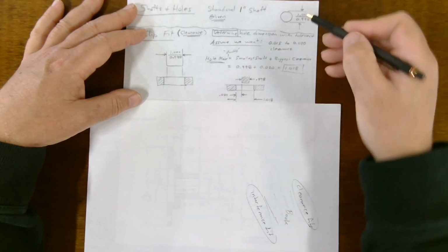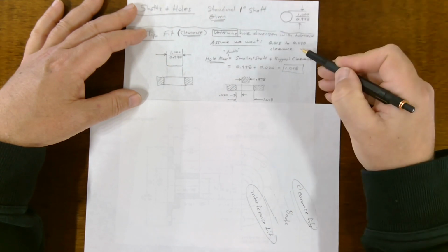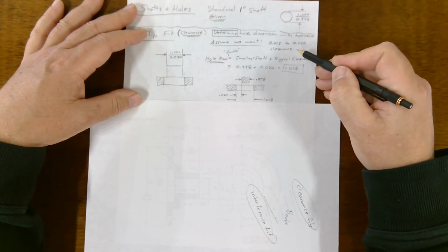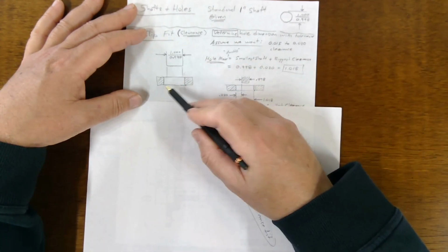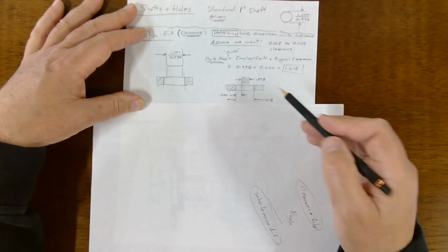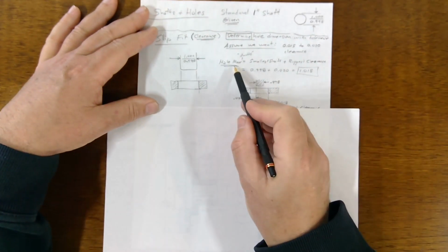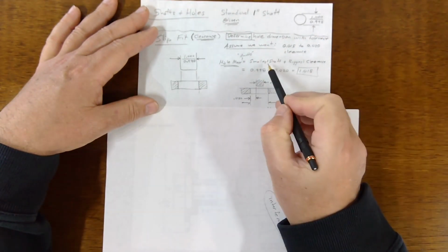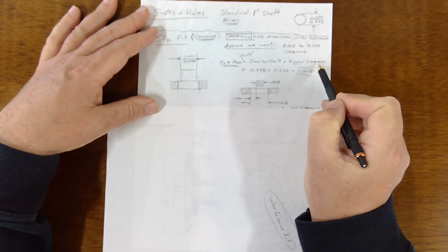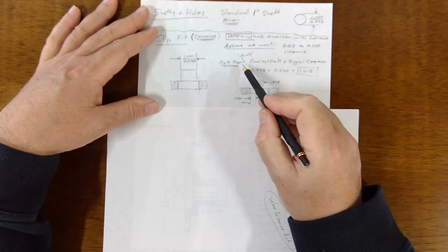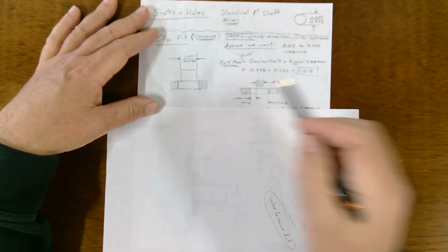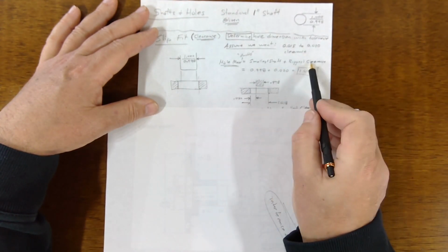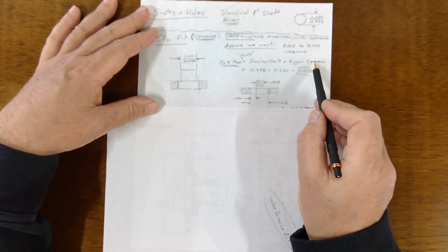So let's say you're given this shaft and you're given this clearance. Okay? How big is the hole? So there's going to be 2 dimensions on the hole, max and min. And I've given you these little formulas here. So hole max is smallest shaft plus biggest clearance. You may have to rearrange this algebraically for the harder problems we're going to do, but for the easy ones, just find the right formula here.